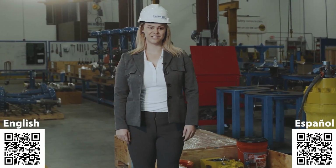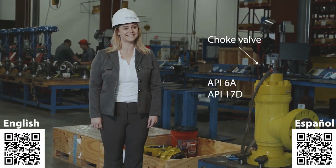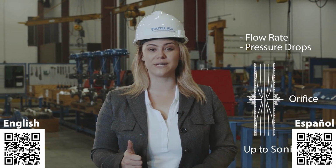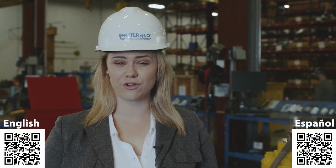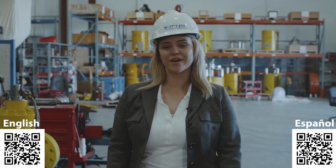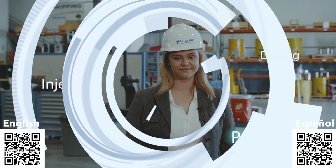In the oil and gas industry, choke valve design is governed by API 6A and 17D standards. Choke valves are used to control flow rate and pressure drops. Reducing the flow channel with an orifice accelerates fluids, sometimes to sonic speeds. For that reason, the design of a choke valve must consider the effects of erosion, high fluid velocity, and significant pressure changes. Choke valves are categorized by their application, including drilling, injection, and production.